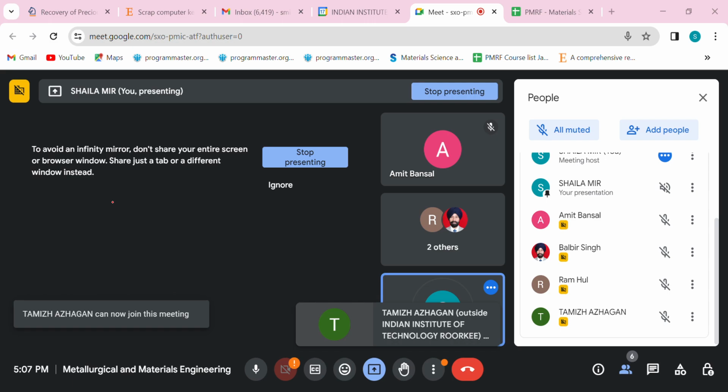Ma'am, what is meant by Brale here? Brale indenter is the name for the indenter that is being used. There are two types of indenters being used in Rockwell. So, does it belong to only one scale, you mean? Yes, it belongs to one scale only. Brale indenter is only used for scale C, for hardened materials.